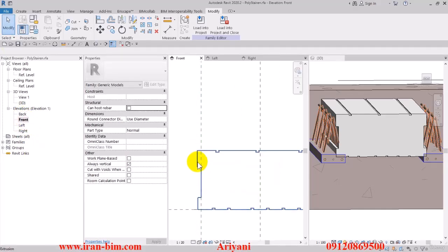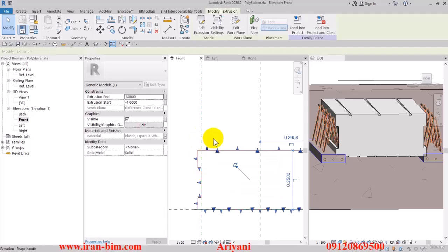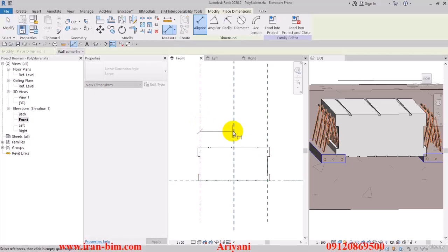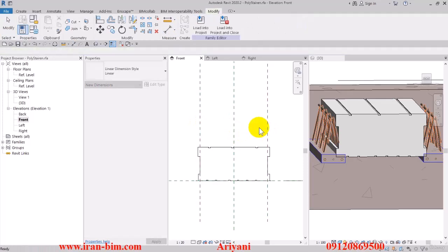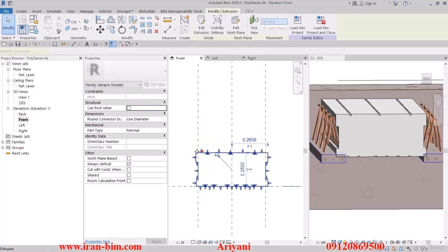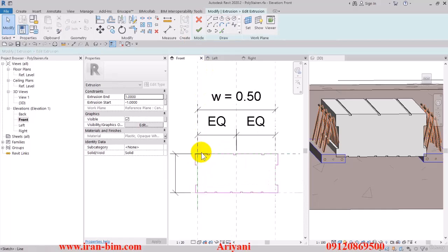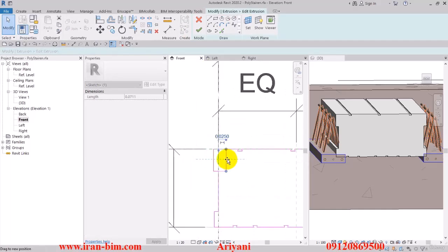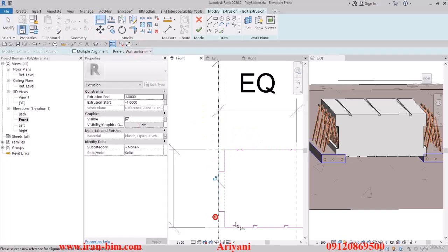And let's see here in the front view, I'll select the measure tool and see what the length of this is. It's 0.5. It's okay up to here. I'll just edit this part and bring these parts on the inner side. Put in 0.02 here and then select align.